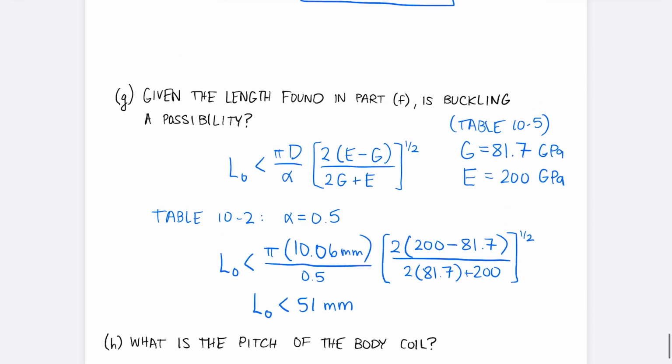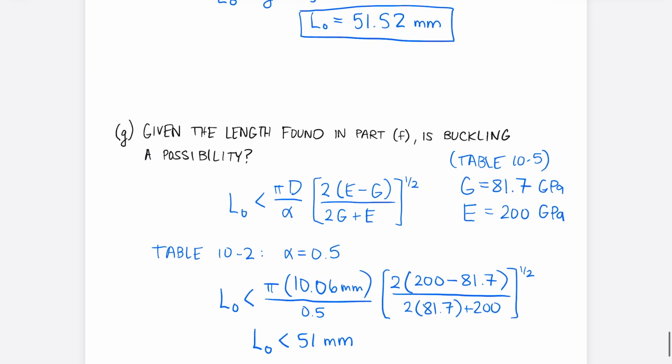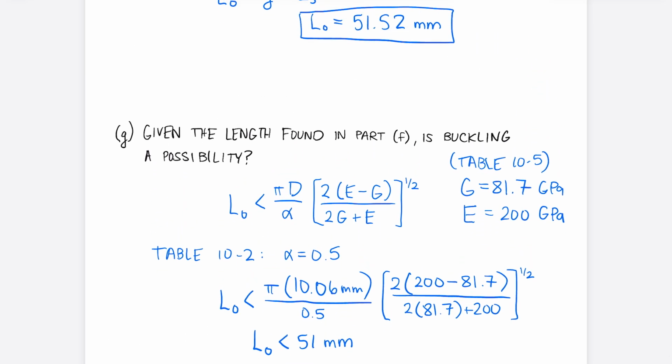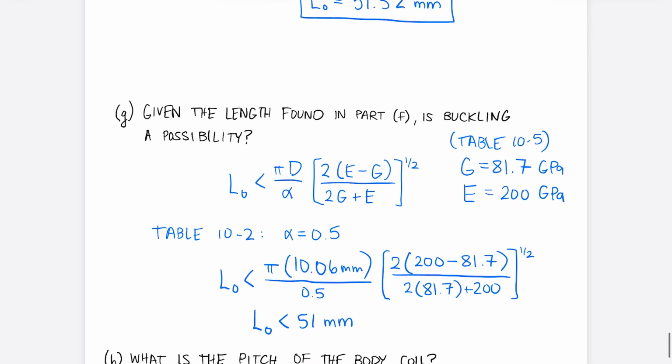Okay, so my free length is just above that. So that means that buckling is a possibility, although I am right on the cusp of being under this.